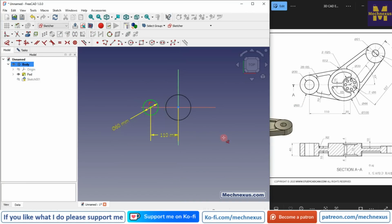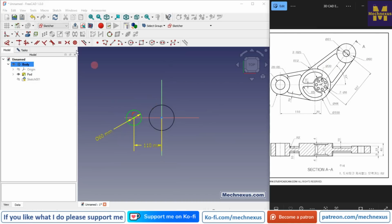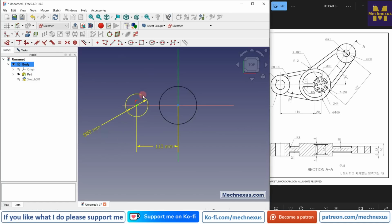and here we can see that this diameter is 60. So provide the diameter, and now we will create this circle, and here we can see the angle of 51 degree. But before that, let's select this diameter and make it construction.